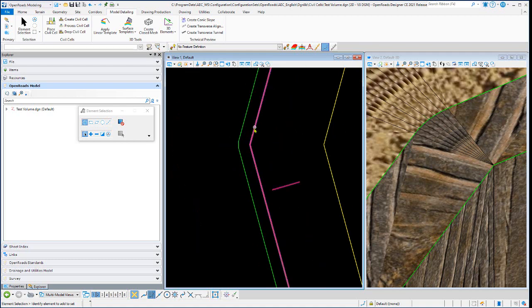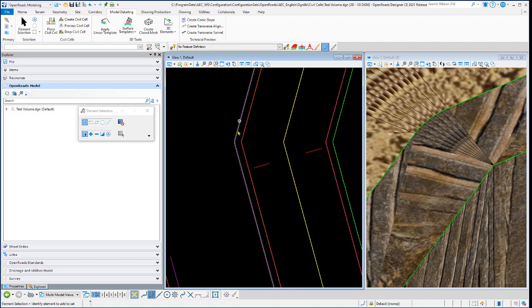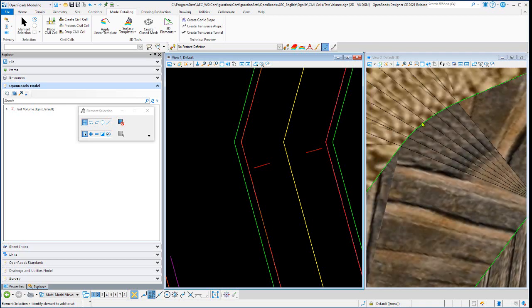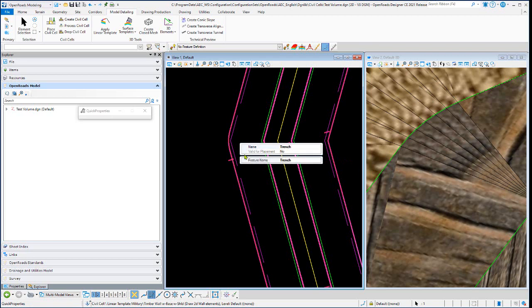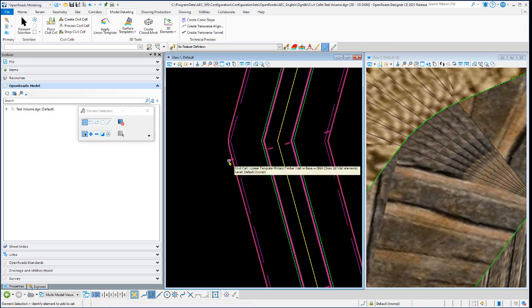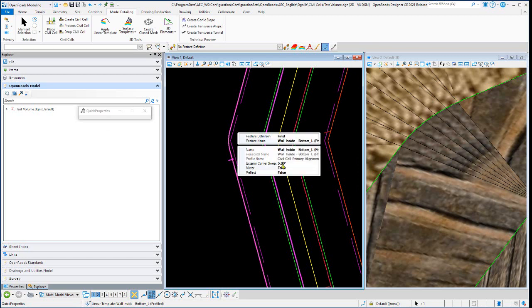So, I think what you could do is potentially draw this outside edge, really just in this area right here, and add a point control if you want to push this. It looks like it kind of rounds it. You can play with this property, not that property. I want that exterior corner sweep angle.